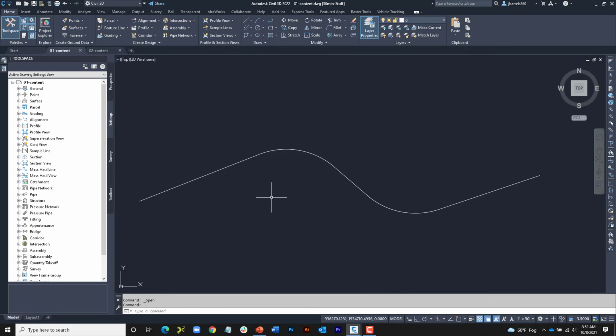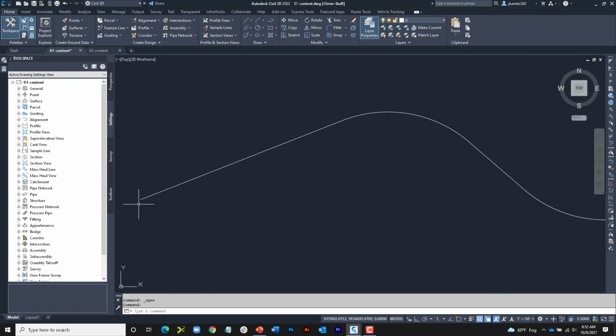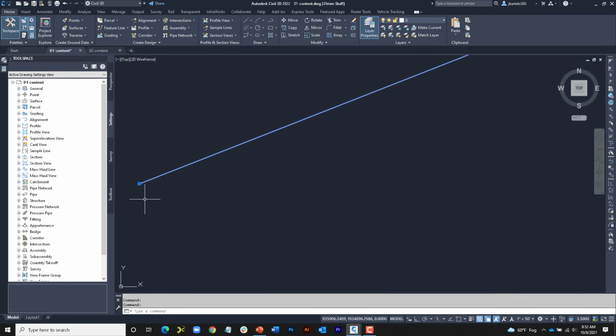We're going to start out by looking at how we can set Civil 3D to check for tangency in our alignment geometry. On my screen, I have a polyline, and I would like to create an alignment from this. This is a typical workflow. We want to create an alignment from objects. Now, I generated this geometry myself, so I know that these curves are tangent to these straight segments. However, sometimes you get geometry from others, and you may not have time to go through and validate everything.